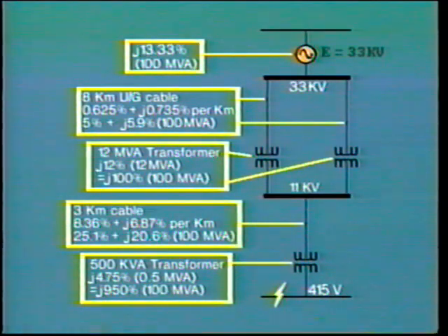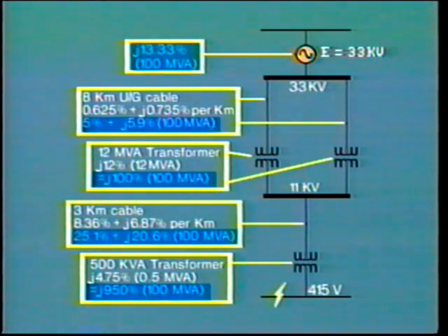We already know that in order to determine the value of fault current, we need to divide the voltage E by the circuit impedance between the source and the fault. E refers to rated source voltage, as this is the voltage which is acting at the instant of the fault. The impedance to the fault is determined by adding the values of impedance of all of the elements in the circuit, not forgetting to allow for any change in the voltage levels. We did this in earlier examples in this tape. Where symmetrical components are being used, we need to take into account the positive, negative, and zero sequence impedances. Let's see what we mean by this.